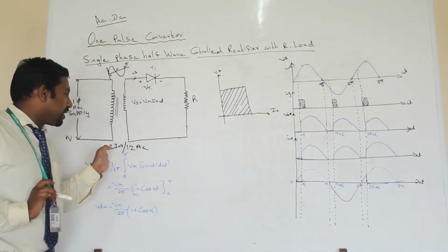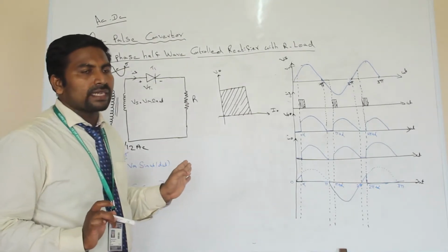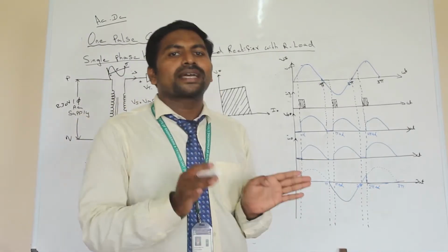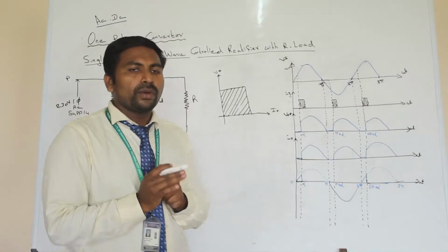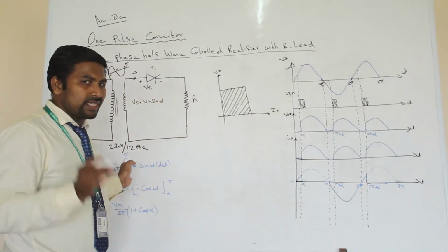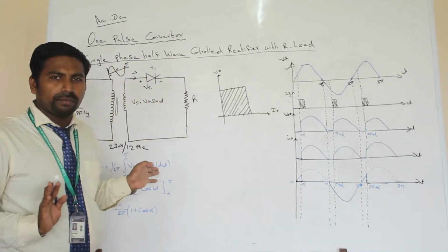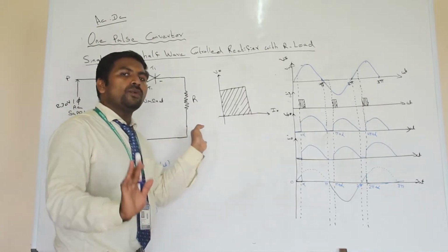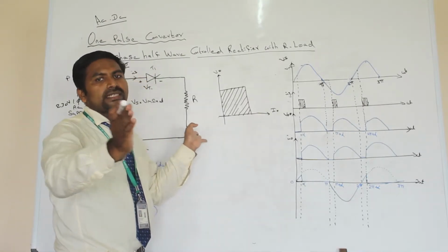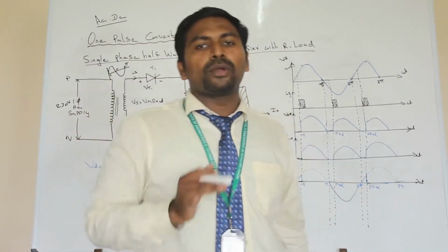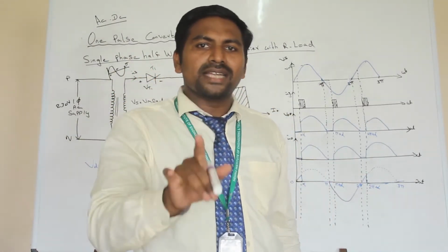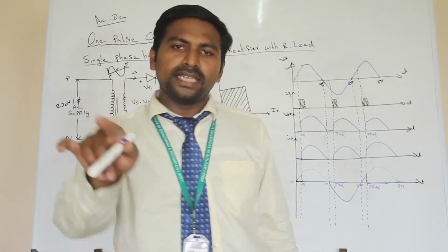Initially we will be giving a transformer. The transformer is used to step down to your required voltage. Your input voltage will be 230 volts. It is a constant input voltage we are getting from the EB. But your required voltage will be 12 volts or 9 volts. For example, we can see your mobile charger. Your mobile charging voltage is a 9 volt DC voltage.